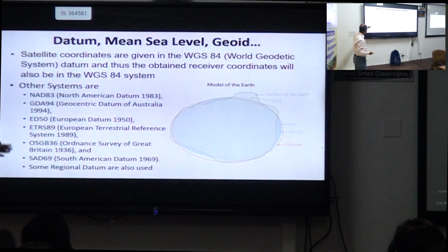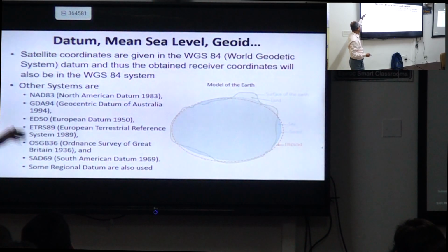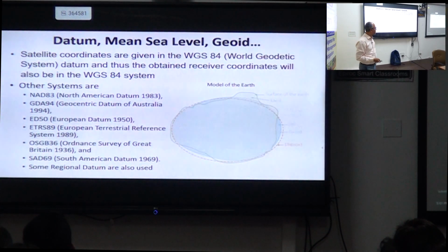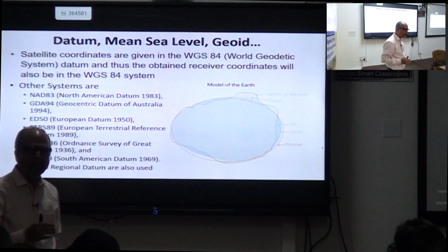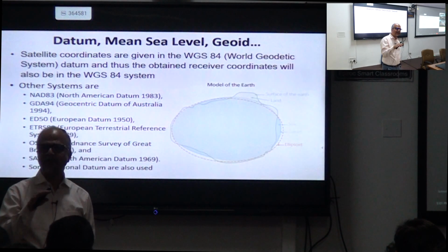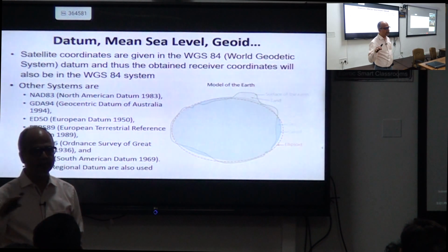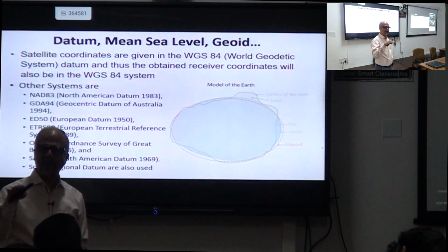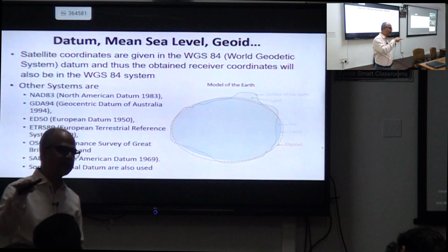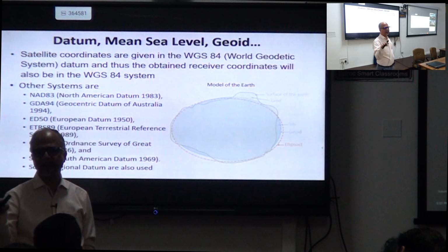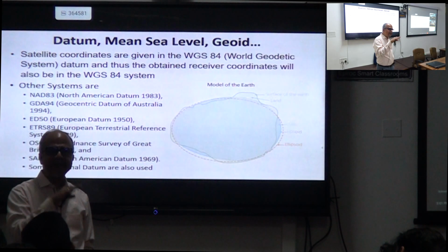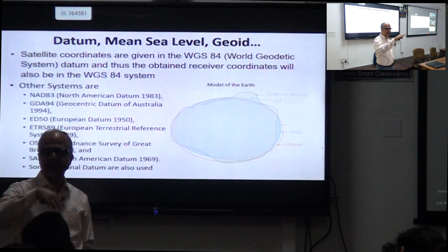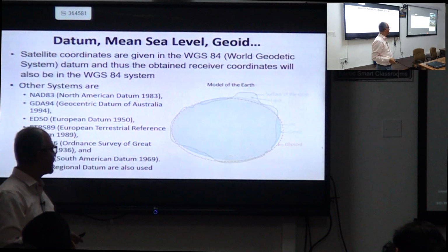And then these datums are being used by different organizations. Some local datums are also there. Now, what is the difference between these actual elevations? Like Survey of India uses a datum. In India, what datum do we use generally? Mean sea level is used. Whatever discipline you have followed, if you have done the basic survey, we all know that for various purposes mean sea level is considered as the datum. Now, this mean sea level is observed for 30 years or so, and then we fix the datum.